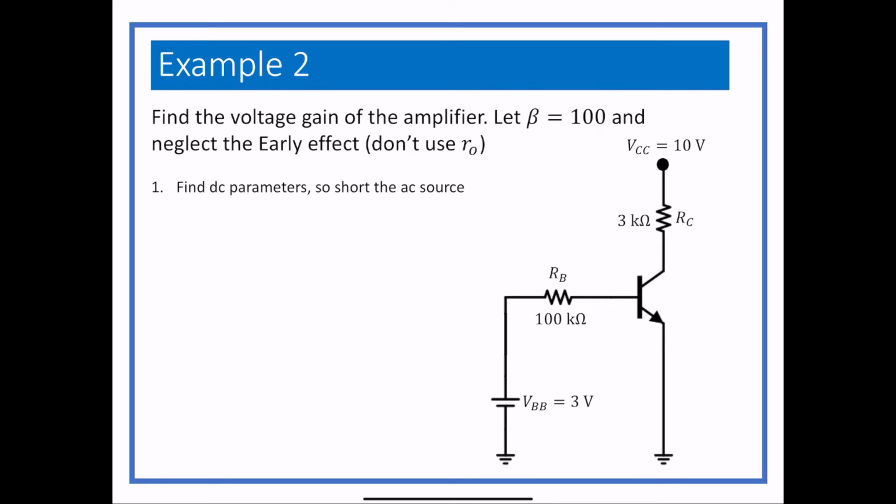In fact, I think for the lab, there's an AC source connected with a capacitor to the DC, and the capacitor just isolates the AC from the DC. So when the AC is on, the capacitors all look like shorts. When the DC is on, it looks like an open circuit. So we can take it out and it doesn't affect anything.